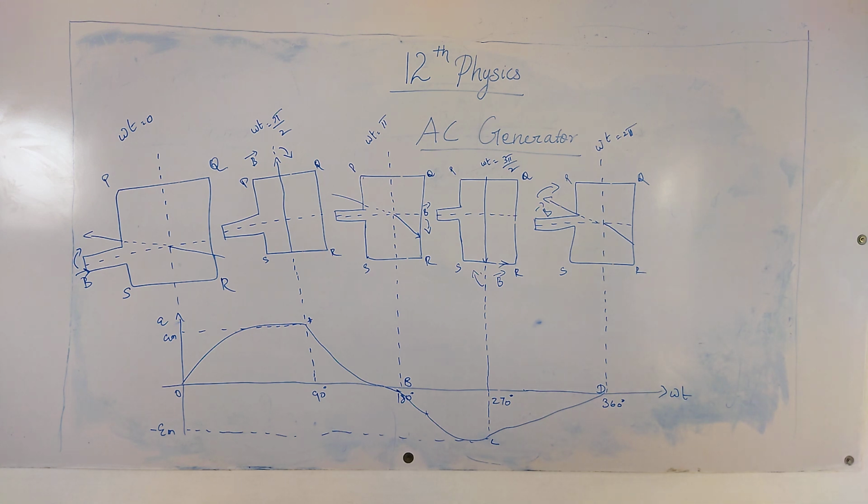Then the installation of the stationary armature winding is easier. The number of sliding contacts is also reduced in this stationary armature rotating field alternator. Then the armature winding can be constructed more rigidly to prevent deformation due to any mechanical stress.